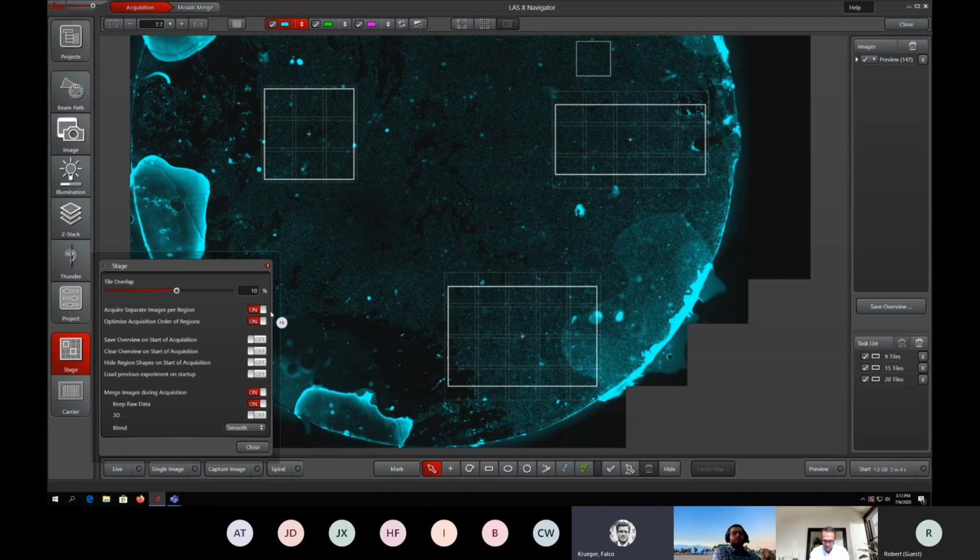Currently my camera is looking at this position here on top. I created maybe this one first, this second, and this as a third region of interest. If I now hit Start and would not have an optimized acquisition, it would start here with region 1, even though the movement takes longer than to this area or this area. That's why the system will automatically make a snake scan to optimize the acquisition order.